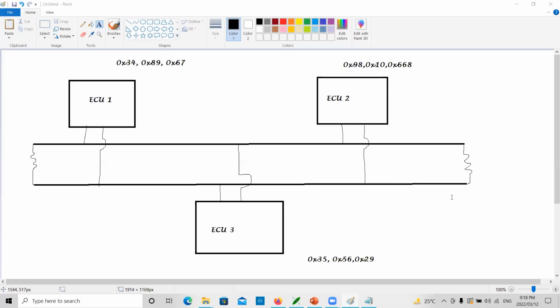If on the bus we have 10 nodes, and within that 5 have messages and 5 do not have a message, what will happen? Arbitration happens between only 5 messages. What I am saying is, the maximum number of messages that will be involved in the arbitration is 10 if you have 10 nodes. Arbitration will happen between 10 messages.